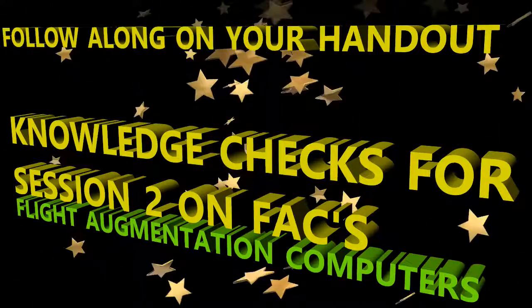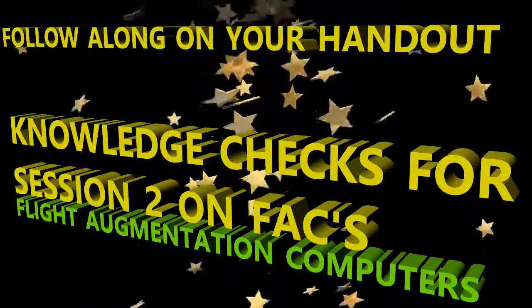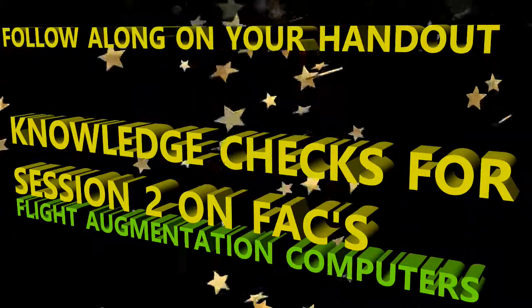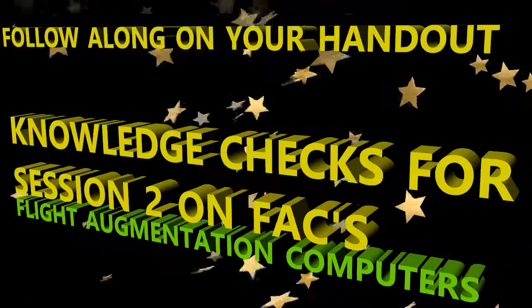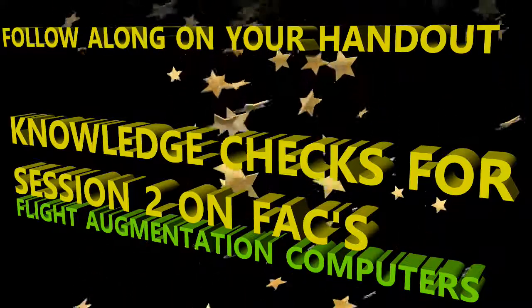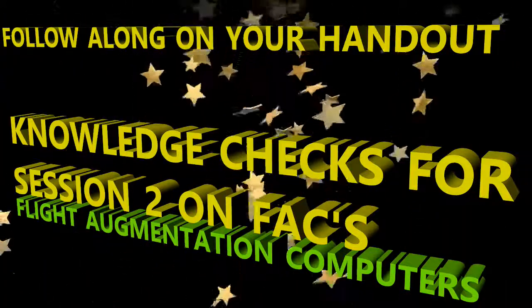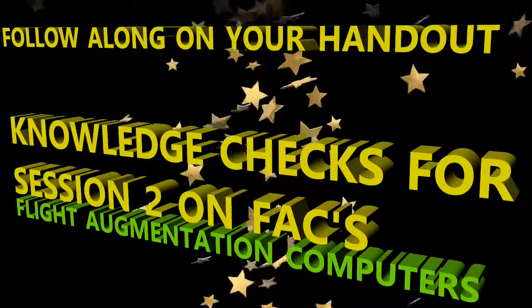Okay, when does the fault light remain extinguished even though there's a fault? Is it when the yaw damper fails? I'm not talking about the system, I just said yaw damper. Or is it B, when there's temporary loss of the FAC? Okay, the answer is the first one.